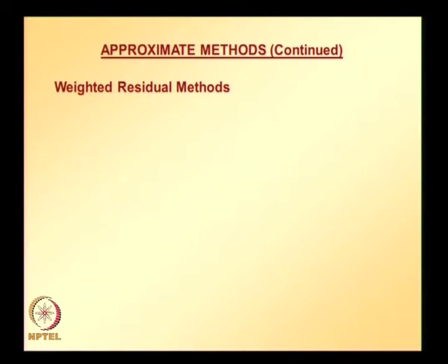And also we looked at length at weighted residual methods. Basically the weighted residual concept can be explained by taking a trial solution like this. When this trial solution is substituted into the given boundary value problem, since this is a trial solution which is approximate, the governing equation corresponding to the boundary value problem is not going to satisfy this solution exactly.